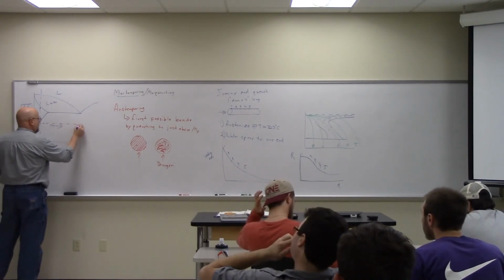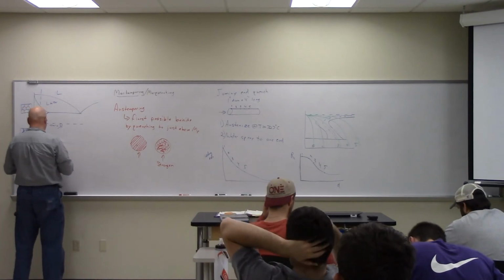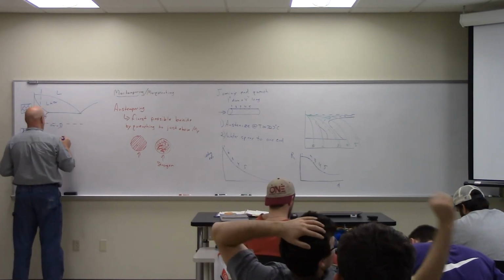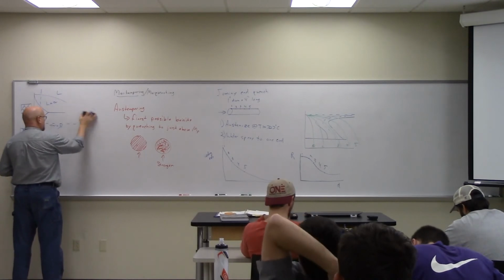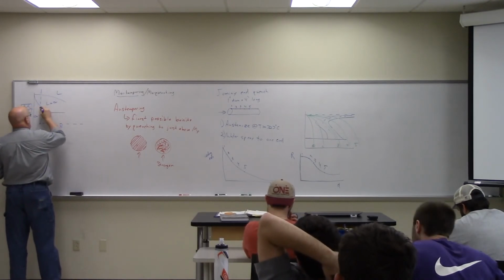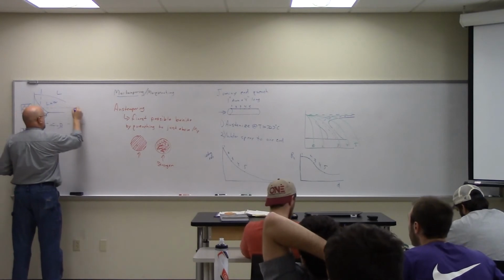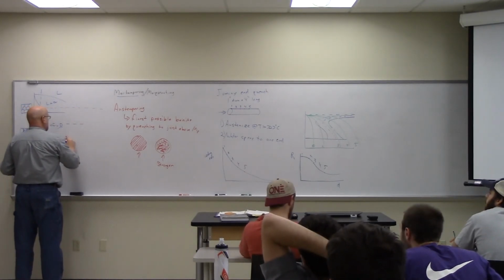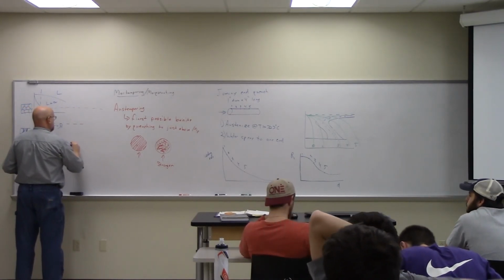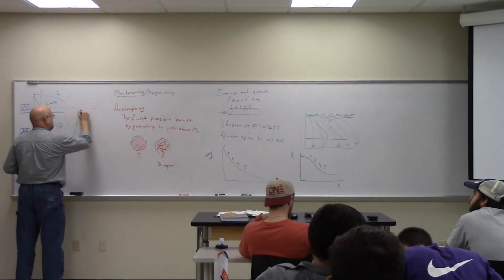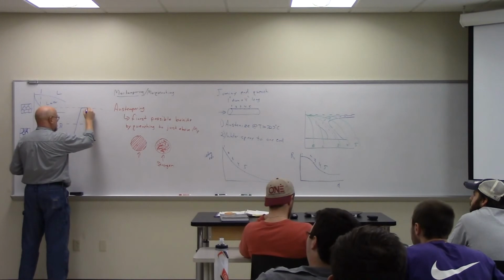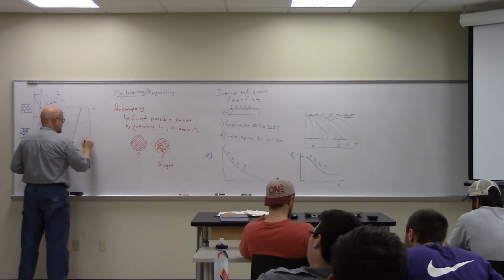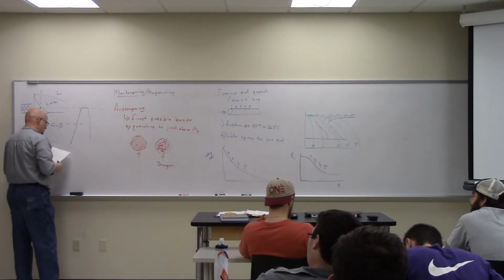I'm going to come up to this temperature, and then if you can imagine my temperature curve now, let me erase all this so I can put the temperature curve on there. I'll put my lines across here. So I'm going to heat something up to the top temperature, get it all converted to alpha, right? Then quench it back down to the region where I care about,